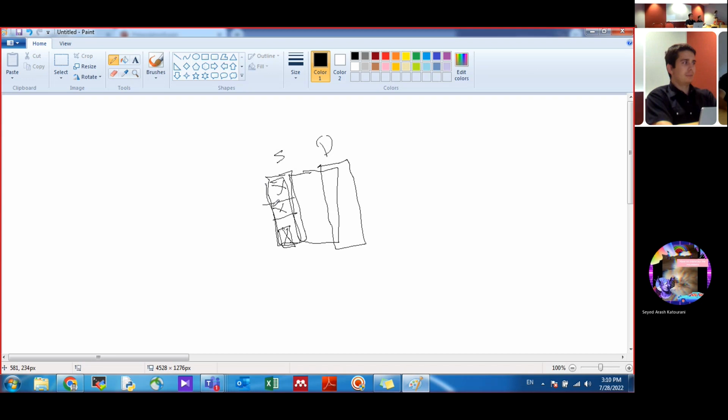What I'm doing right now is this: if you have a multi-finger device and you add another one here, it is another source. What I would normally do is put all the vias here, take my wire out, and wrap around to get somewhere else, and do the same thing here.